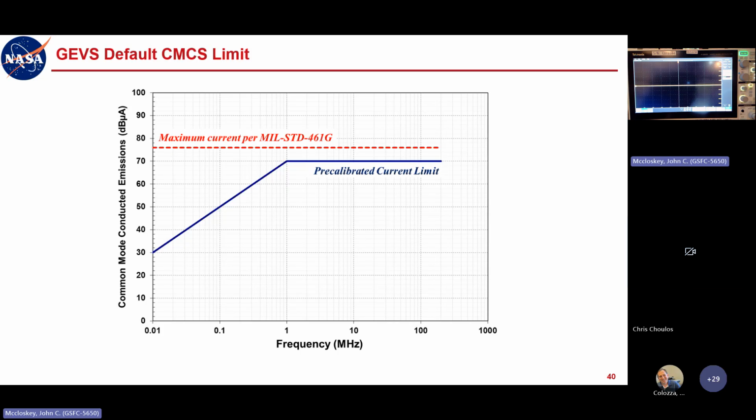So we would expect that we would need a signal generator setting on the order of about 108 dB microvolts. Now that's our VO. The actual VG is going to be 6 dB higher than that. But to get an initial idea of where we should set the signal generator, 108 dB microvolts is our starting point. And as you get higher up in frequency, you'll have some losses and things like that.